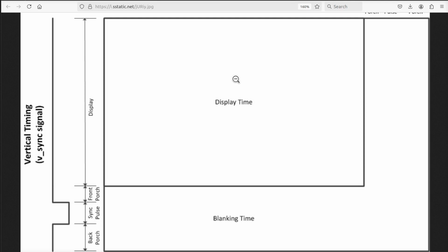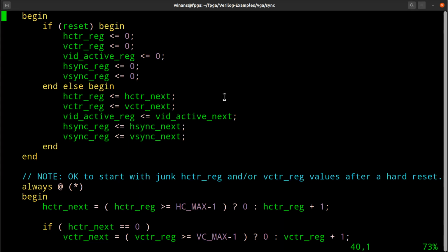But it doesn't really matter what you do, because when you start up, the monitor is looking for synchronization signals and measuring them to determine what format the video is supposed to be in, how many rows, how many columns, how to scale it to fit on the LCD. Modern monitors work that way. So it really doesn't matter where we start.